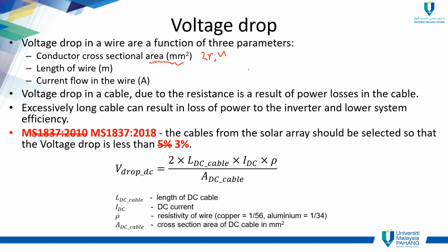Okay. Based on the standard, I mean the Suruhanjaya Tenaga guidelines, for the air conditioner, the cable size to be used is 4.00 millimeter square. Okay, it's 4.0.